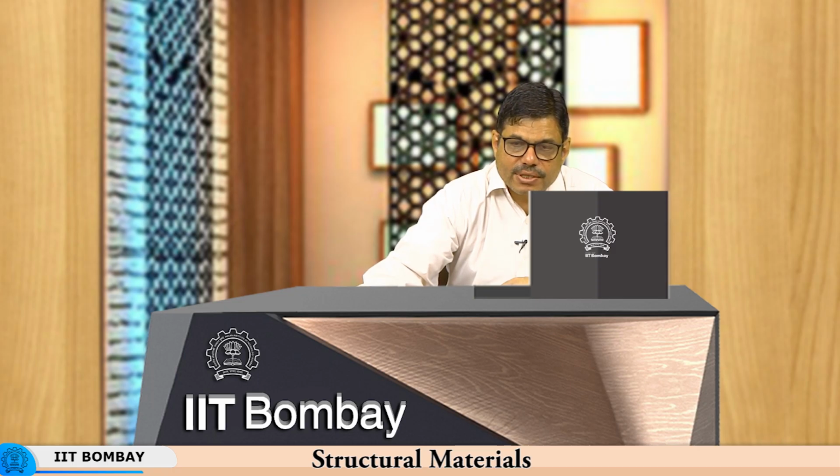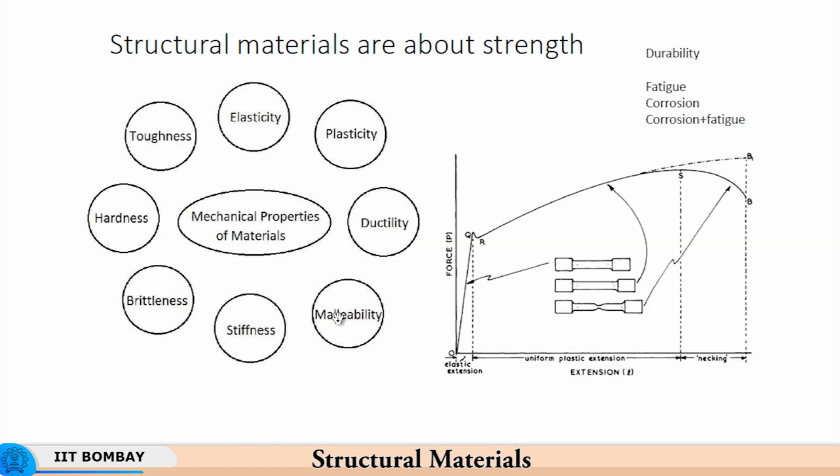And when the material fails, or when the cross sectional area starts getting depleted, the load carrying capacity of that cross section diminishes, and that is why the curve moves downwards. So you have these parameters, these quantitative metrics of strength. So you have yield strength, which is point Q, which marks the transition from elasticity to plasticity.